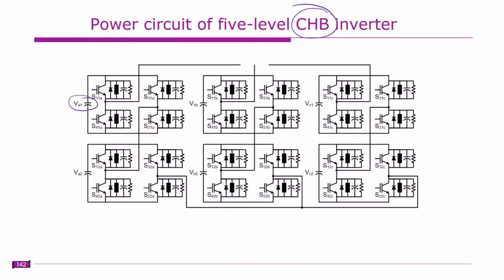In one of the classes, we discussed that with triangle carriers we have better harmonic cancellation in double-edged carriers rather than single-edged carriers, right? We discussed it in one of the classes. So in most of the carrier cases, rotation technique method 2, all are triangle carriers only.